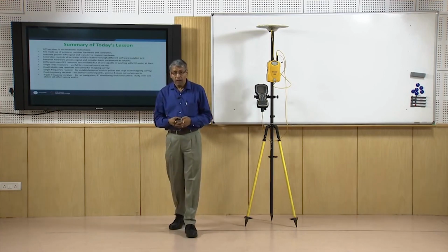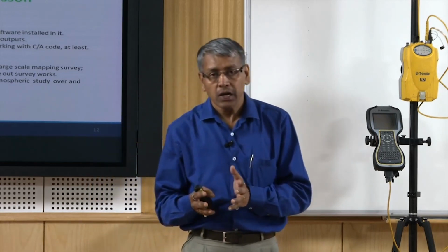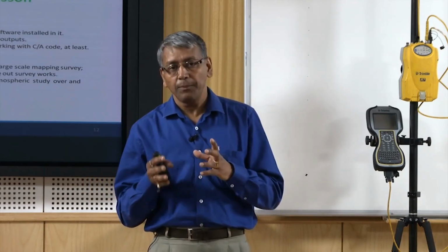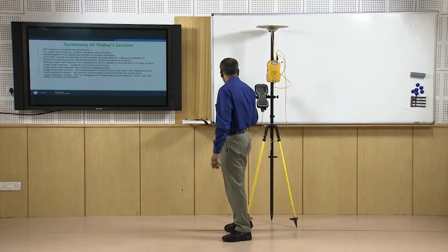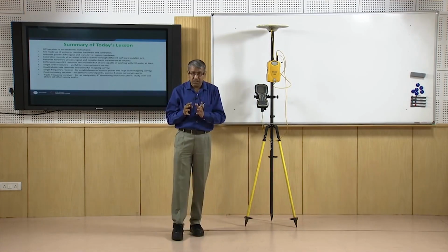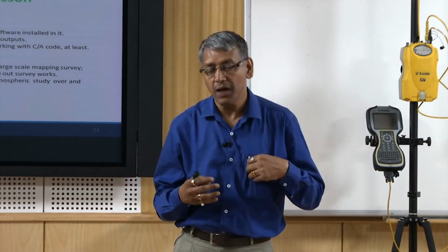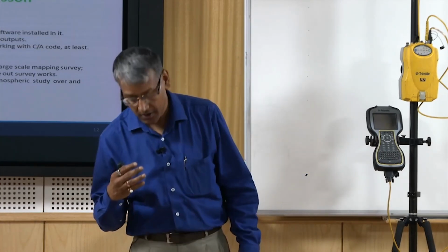The antenna receives the GPS signals and transfers them to the receiver hardware as per the instruction it receives from the controller. The controller also controls the GPS receiver hardware by making use of the software that is uploaded within it. Now the receiver receives the signals from the antenna as per the parameters set by the controller, and then it processes the signals and provides the basic parameters to be used further.